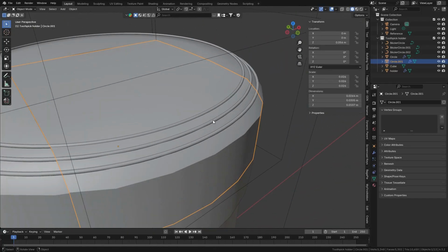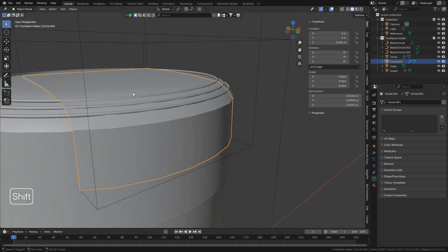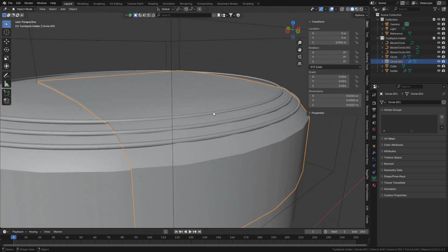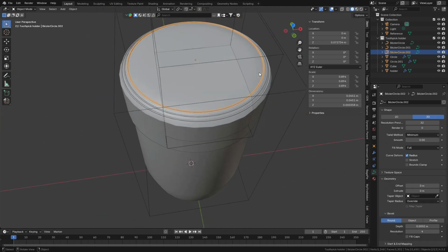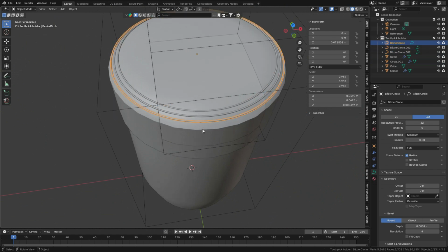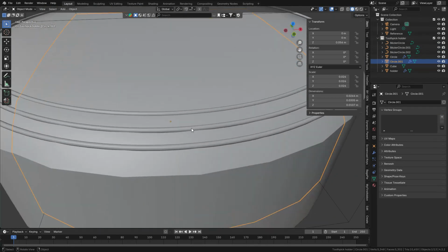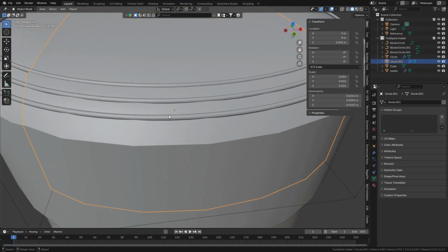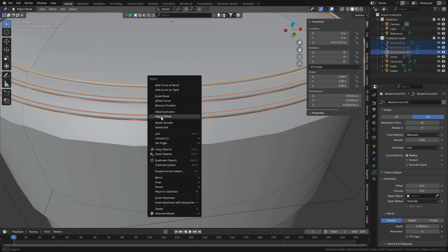Alright, so then now what I want to do is that if you observe that whenever we open this kind of toothpick holders, a part of this goes with it. In order to do that, you have to kind of cut these rings and make some of them be parented or controlled to this. One way we can do that, and that's what I'm going to show you here, is we select this curve here, shift select this curve, shift select this curve as well, right click, go down and convert all of them to mesh.